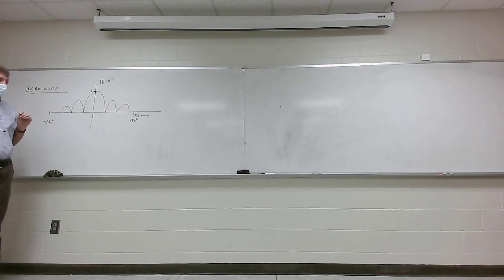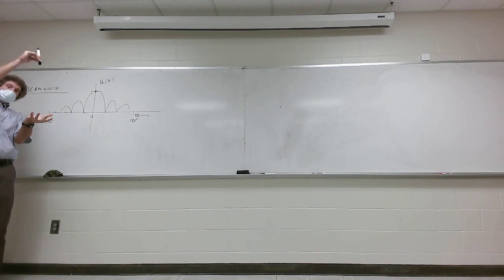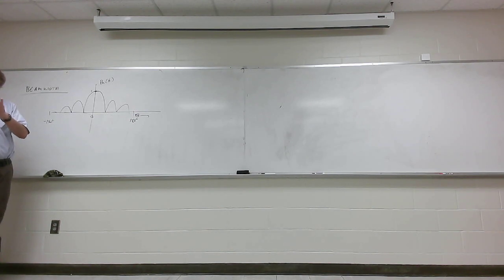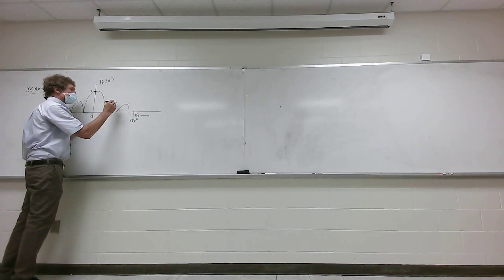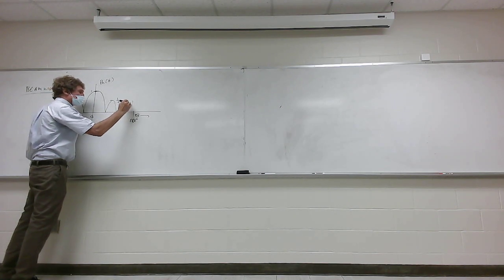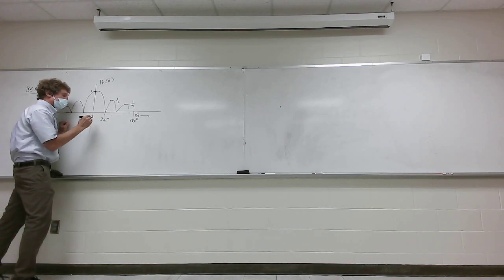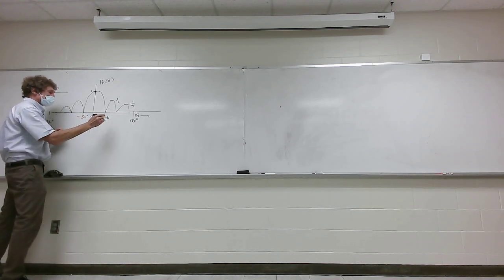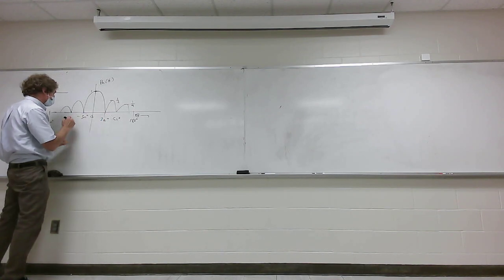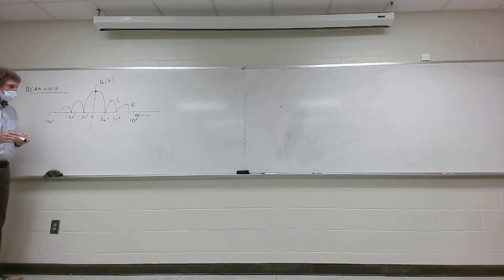It would be versus angle, but this angle is called the measurement from the boresight. If you have a dish antenna, it's the measurement from a vertical, straight in the center of the antenna that's going out perpendicular to the area of the disc for the dish antenna. It's measured this way, and it's not a function of feet, but I don't want to spend too much time on this. Let's assume this has a value of 1/2, this a value of 1/4, just for heck. And say this is 30 degrees, this would be minus 30 degrees, say this is 60 degrees, minus 60, and so forth.